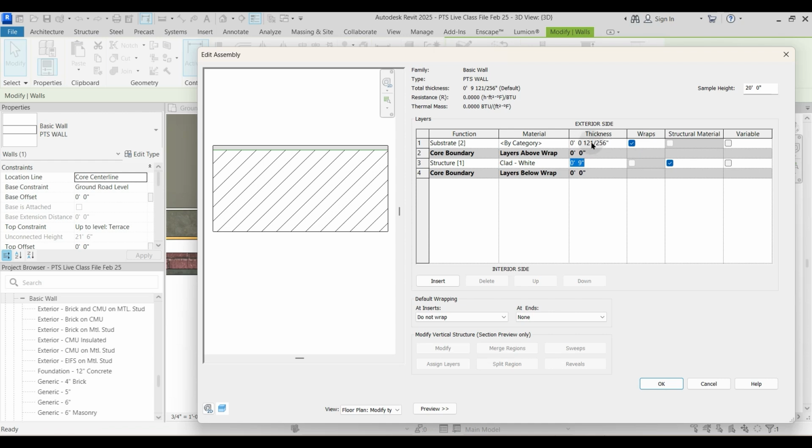But this is the ugly fraction. So what if I want to type exactly? So I will write that 12 mm is 0.5 inch. 1 inch is 25 mm, not even exactly, 1 inch is 25.4 mm. So we will follow certain standards. So I will just type 0.5 inch and enter. So that will accept 0.5 inch.